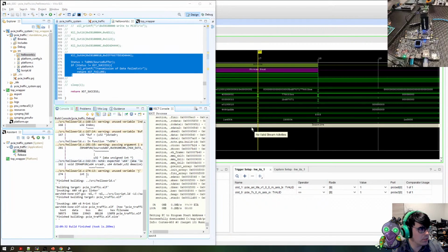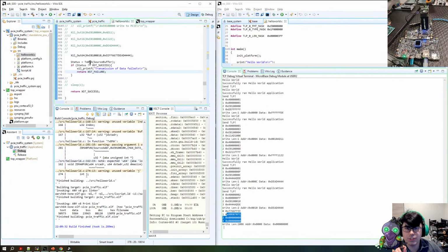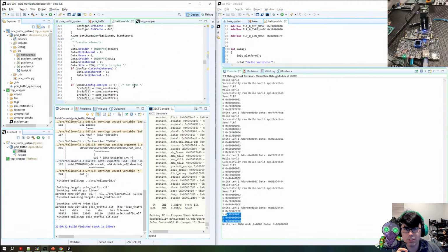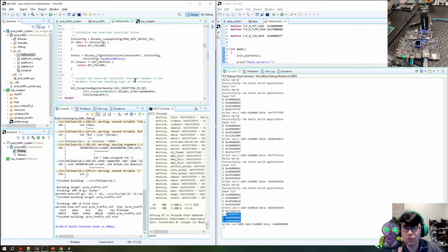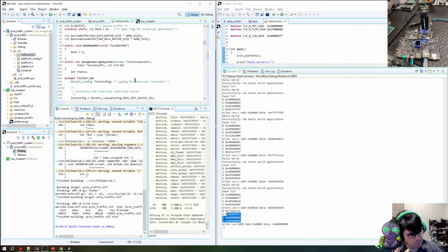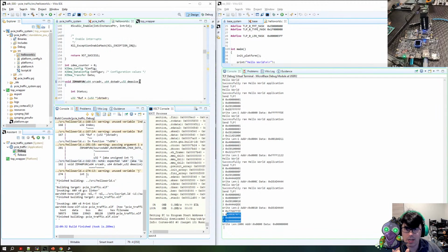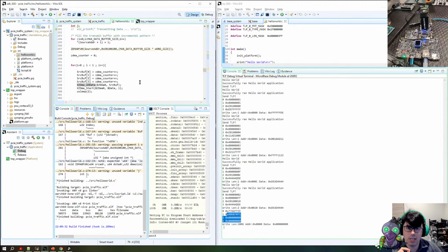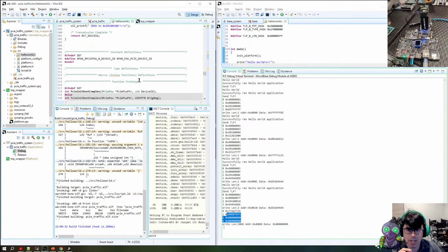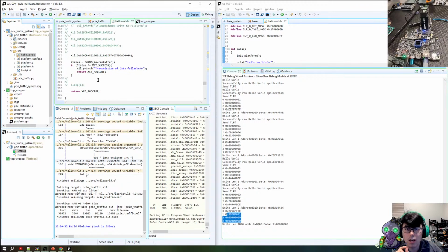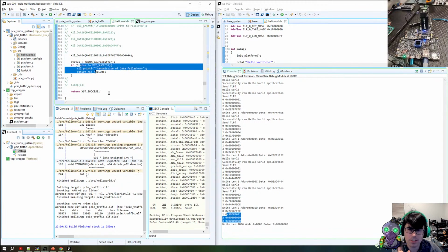Okay, so we're going to try to use some ZDMA. ZDMA is our DMA buffers built into the system. There's actually 7 of them. We're just going to use 1. Actually, there's 16? There's 16 of them, I think. 8 of them or whatever. I have 8 listed here. But you can interlace them to basically do constant data transmission. That's kind of like how a really good scatter-gather driver will come into play to really get data between your root complex and your endpoint. But we're just going to do a single instance of the DMA transaction. Go see how it works.